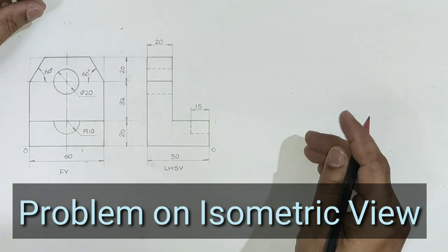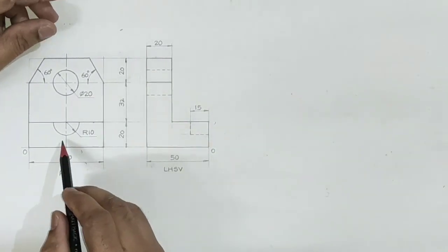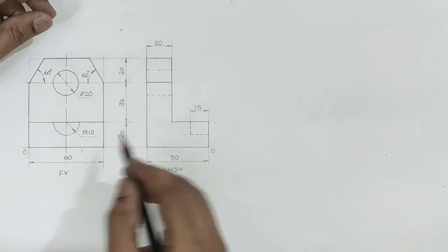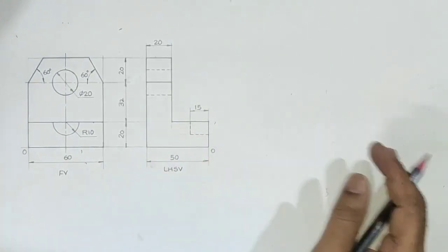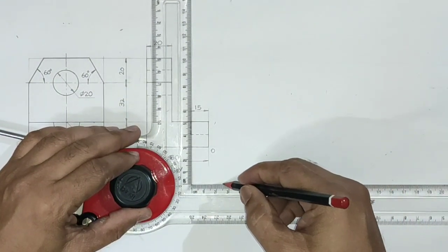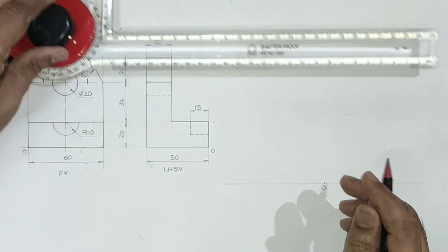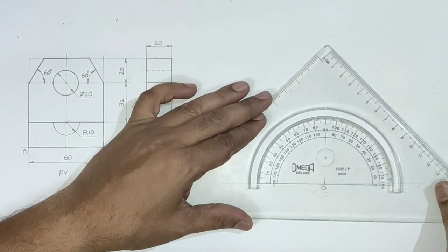Problem on isometric view. These are the two views given for an object, front view and left hand side view, and we are going to draw the isometric view for these given two orthographic views. First of all, draw a horizontal line, then take one point on this line as origin, then draw two lines at 30-degree angle,